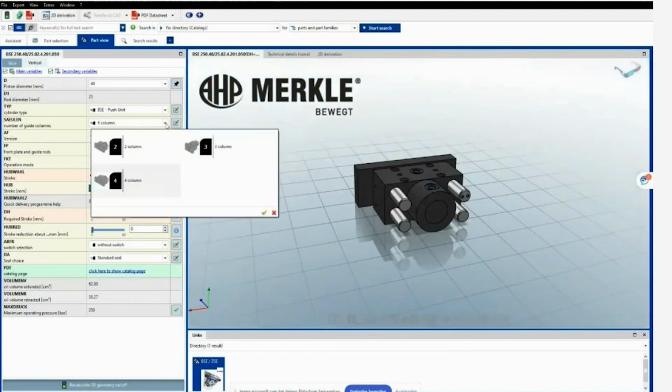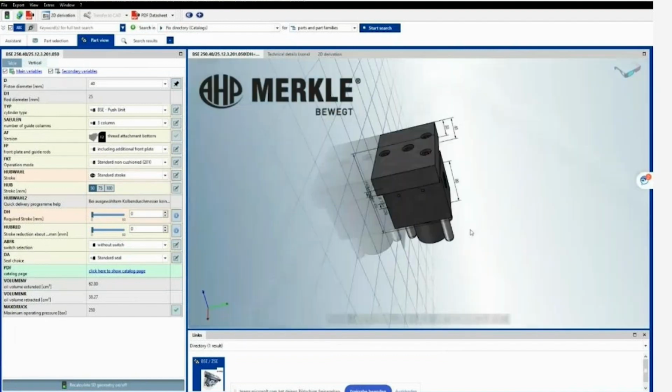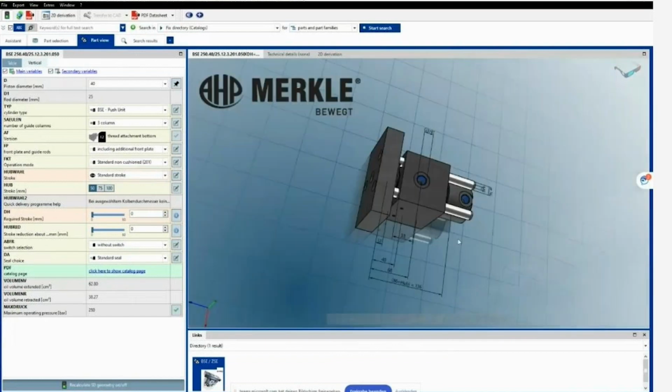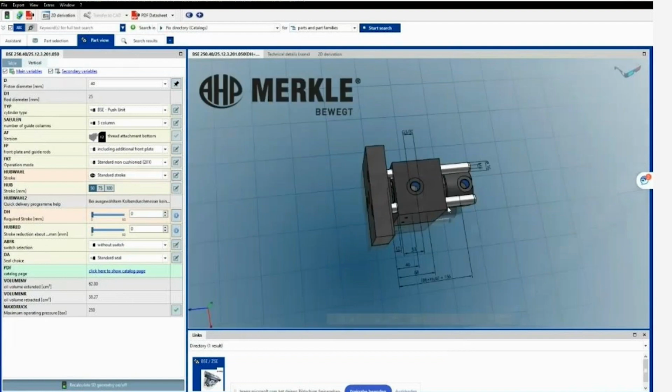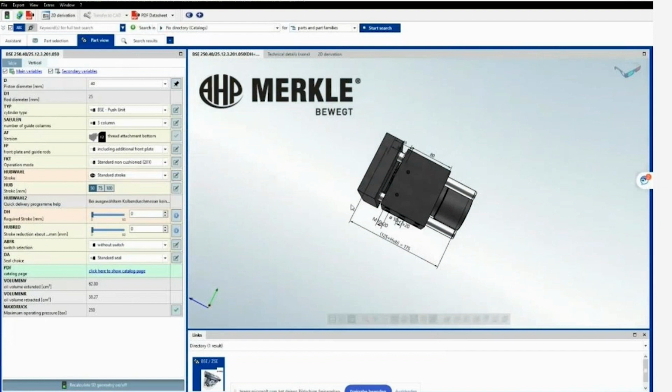So we have it with 4 guides, we have it with 3 guides, for example. We know that in plastic mold making, we do our cam slide by ourselves. We put the sliders on the lateral side, and then we move it with a pin or a hydraulic cylinder. So in die casting, to be more robust, we build the cylinder into the slider, and this is much more robust and stronger to work in this kind of environment.